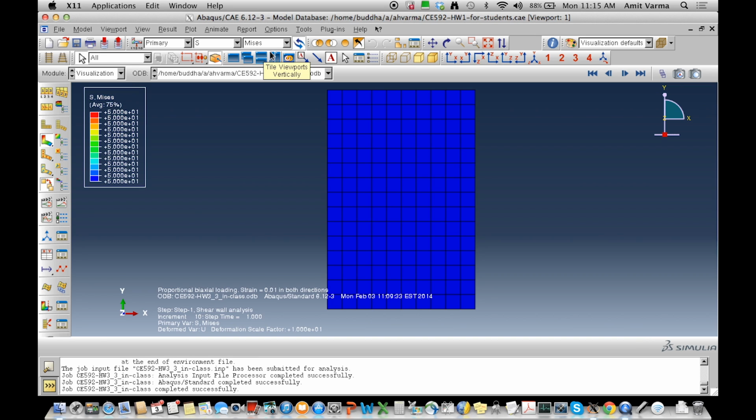So nobody can fool you now because you'll always be able to look at the effective stress and see if it is satisfying the J2 material criteria. Because that's what we did. We programmed a material that has J2 dependency, which means that if it is yielding, the square root of 3J2 will always be equal to 50. Whatever it is that you specified in that tab as 50. If you had specified 55, it would go up to 55.